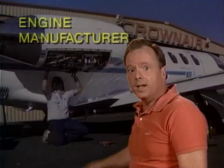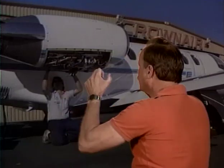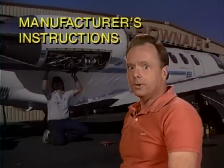All right, let's take a look at the recommended operating time between overhaul. Who determines that? Once again, it's the engine manufacturer. Now let's assume you're removing a turbine engine for test cell operation. You're going to take this engine off and put it on a test cell. How do you do it? The answer is according to the manufacturer's instructions. And so you can say manufacturer's instructions for almost all of these questions and get them right through here.